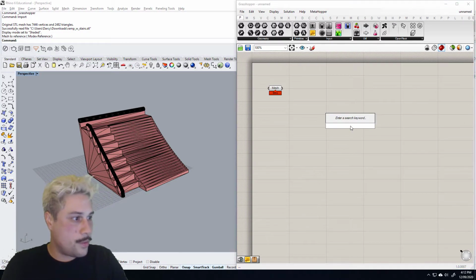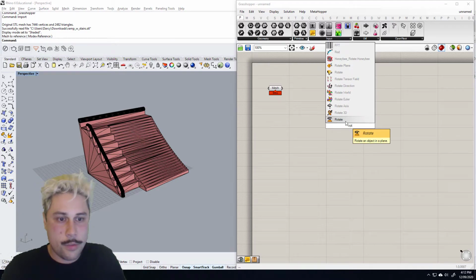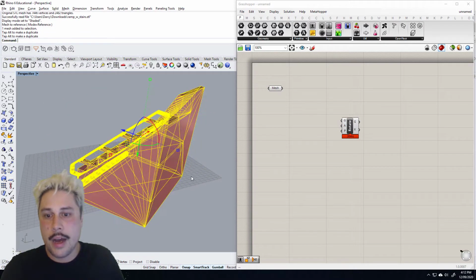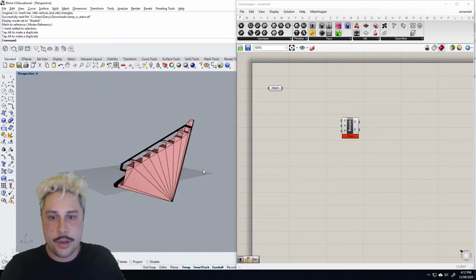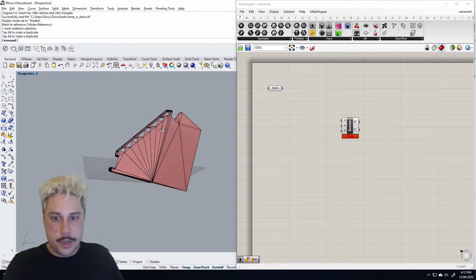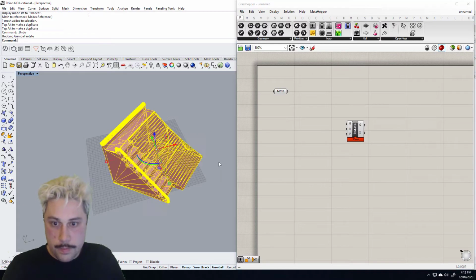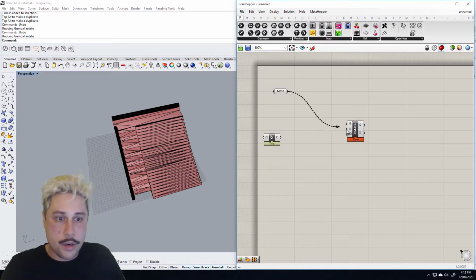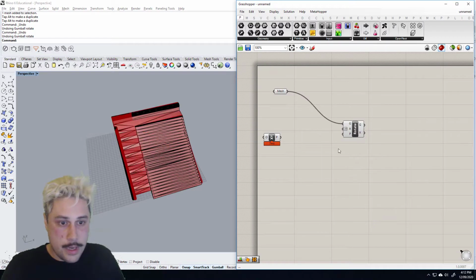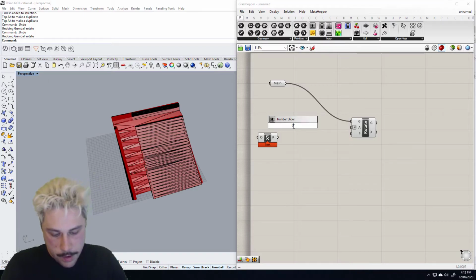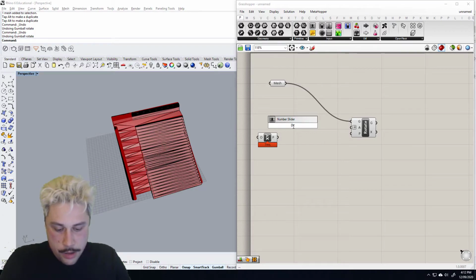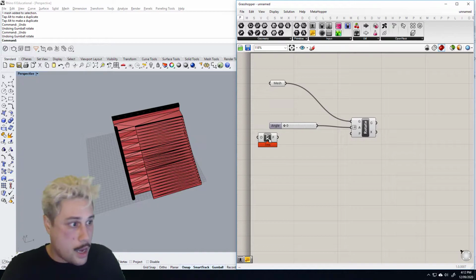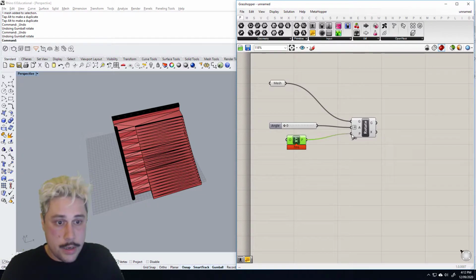So what we're going to do is essentially find the best orientation of this part to sit on a 3D printing bed, so that the support material that usually comes down from it is the least. So I'm going to set up a series of rotations and get this workflow up. We'll go from 0 to 359. We don't want 360 because it's essentially 0, in the XY plane. Cool.